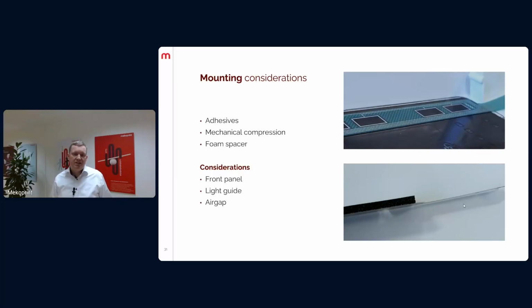And depending on the adhesive type and your requirement, we can choose between a laminated adhesive or a printed adhesive. The big advantage of a printed adhesive is that you have more options in terms of which areas you want to cover with the adhesive, and which you do not want to cover with adhesive.